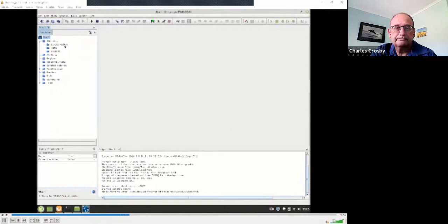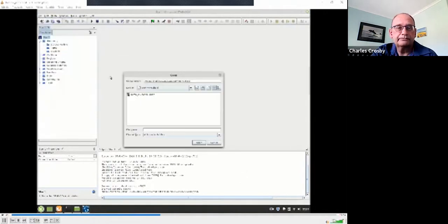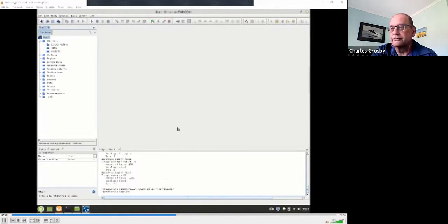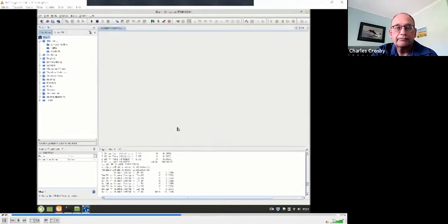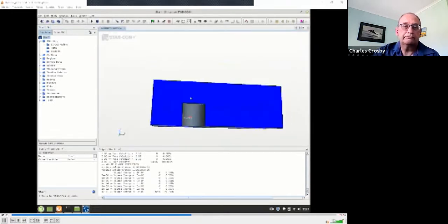And remember that I also mentioned earlier that Fluent's .msh mesh file format is quite widely supported, and it's entirely possible for us to import that existing volume mesh, which is generated with ICEM CFD, into StarCCM Plus. There we go. We've seen this geometry before.